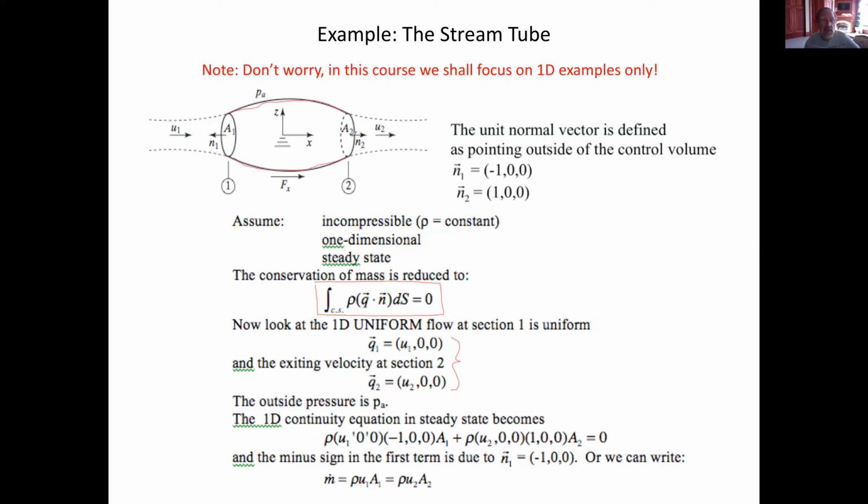So next I have to go here. So here the unit normal is +1. This is the unit normal. And then the area is A2. And then the velocity component is still positive in the x direction. It's the same thing here. So that's the velocity component. I multiply it. Okay, this is vector algebra. And I end up with this, because one is plus, this is minus, and this is plus.